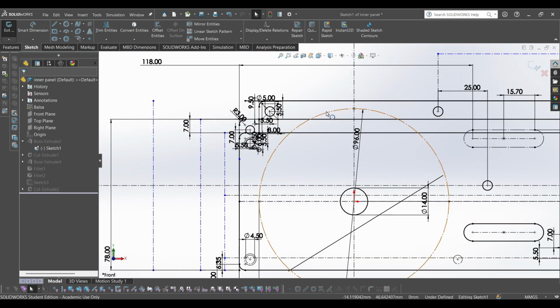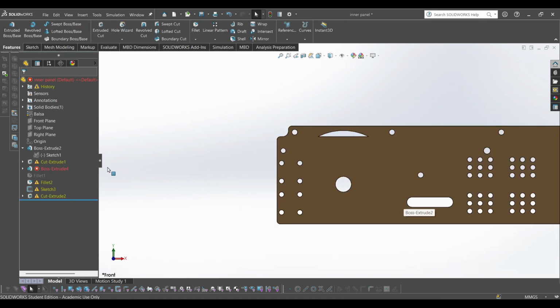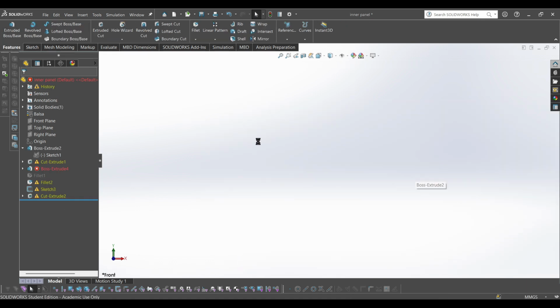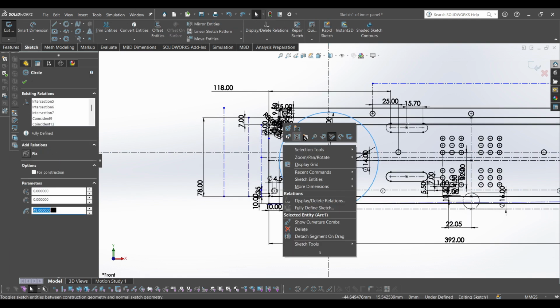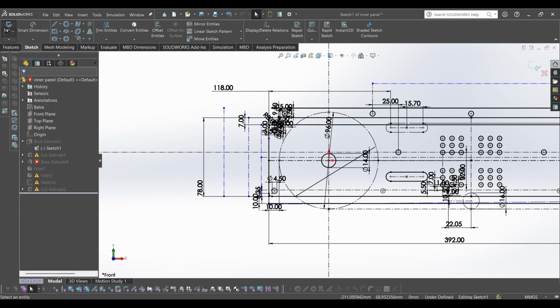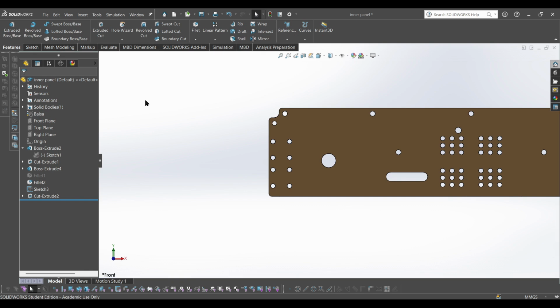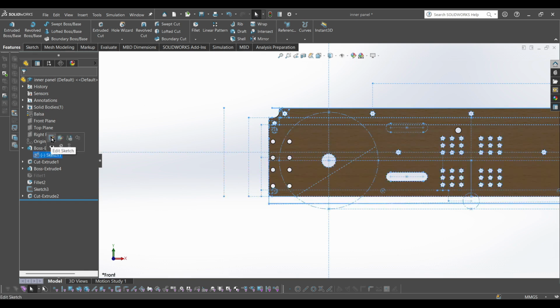Because if this was not a center line, then this would happen. You can see how it's taking a while and there'd be all these different errors. And that's because, as I mentioned, if it wasn't a center line, I would have to go back and select every single area around it when I was making the feature with the sketch regions.